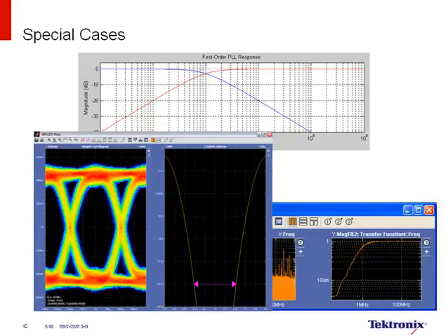If you want the eye diagram closure to correlate to the BER at 10 to the 12, then what you need to do is run the eye diagram analysis till you get 10 to the 12 UIs, and then you will see very strong correlation between the eye diagram and the BER bathtub.